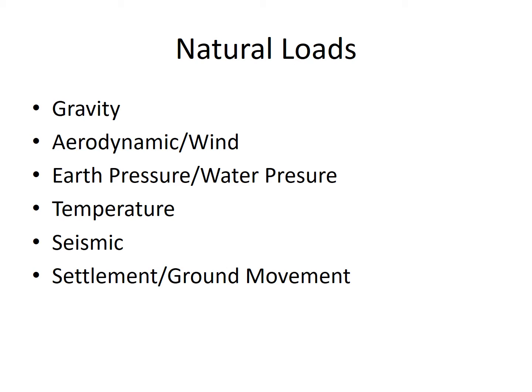Okay then, so if we look at natural loads, the loads that occur from nature, they can take several forms, and we dealt with in the previous slide the gravity loads, so the loads of a person sitting on a chair, the weight of the chair itself. So those are the variable gravity loads, and they find their way into the structure through the floor slab, for example. Now that floor slab has its own self-weight under gravity, and that's a permanent gravity load.